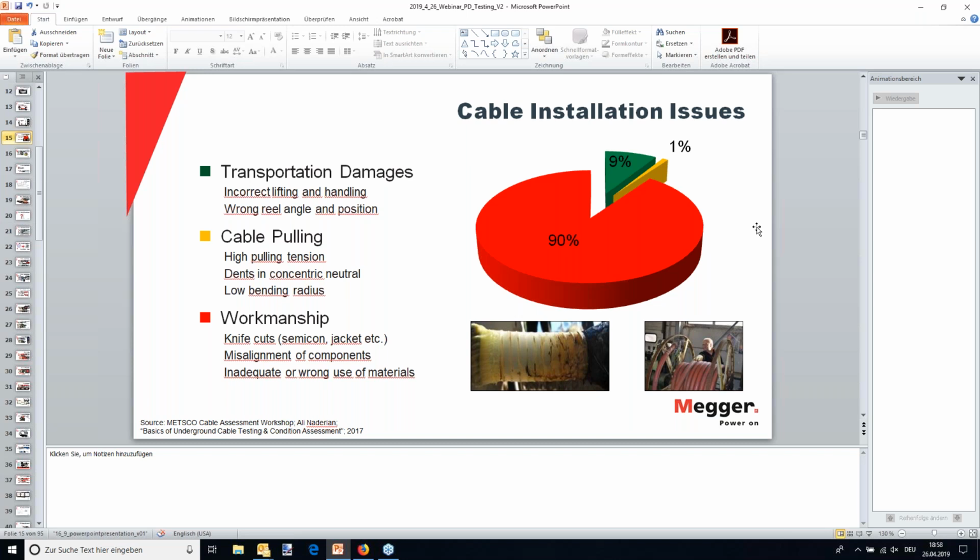Well, the important measurement is the inception voltage. It should always be above U naught. That is one of the main things where you say that splits or severs how many, or critical is at operating voltage and below, and per definition not so critical is above operating voltage. And then it comes on top: how many counts? What's the event count? How many pulses do you get? What is the inception voltage really? Is it closer to U naught? Is it far away from U naught?